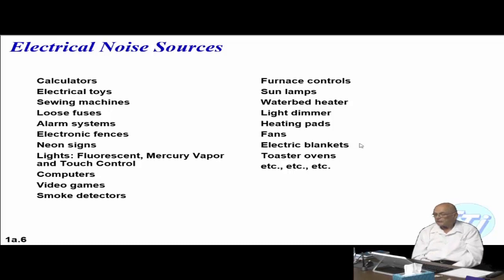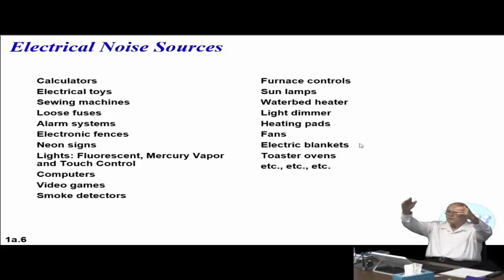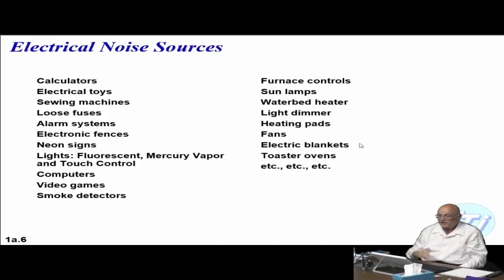Not only that, if you take a look at the wiring in the wall, what kind of wiring typically do you have? You typically have AC, don't you? 60 hertz AC. A lot of times you'll get 60 hertz and 120 hertz as being noise problems, which can be fairly significant. If you look even in this room, you've got fluorescent lights above you. So by moving all the equipment to the center of the room, they were able to have only the people that were necessary in the room. Because as you walk around, you're a capacitance that changes the coupling.